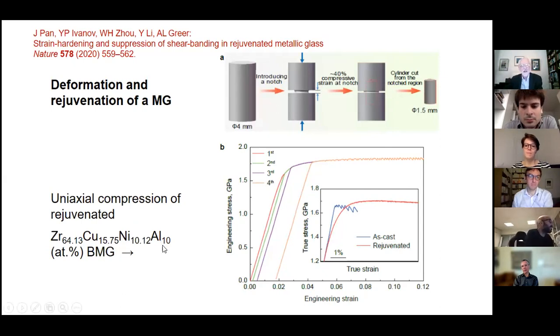And the result is rather astounding from the point of view of the metallic glass world, because this could equally well be stress-strain curves for a polycrystal. You go up elastically, you could unload, you come down elastically, but if you start to go into yield, your flow stress increases, you unload, and then when you reload, your flow resumes, but at the increased onset stress, which of course is classic strain hardening. And you can get quite a significant amount of this hardening behavior.